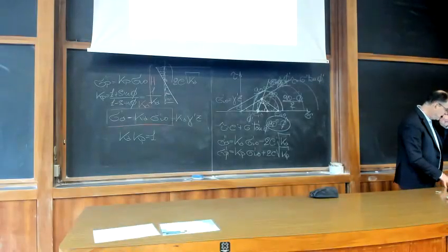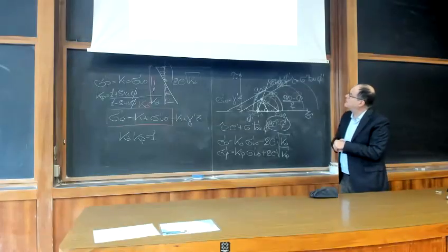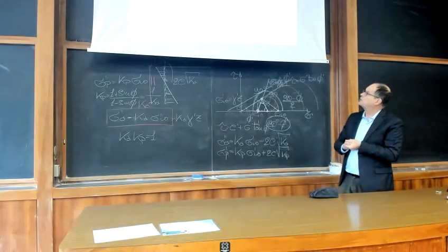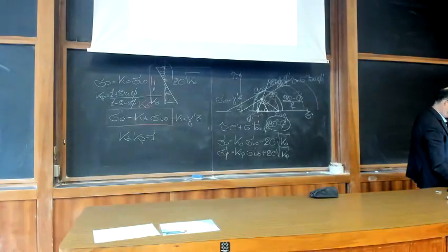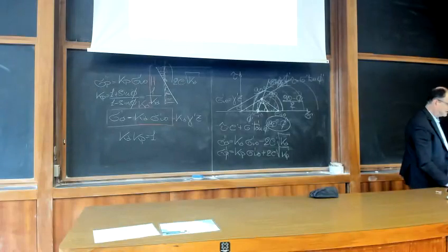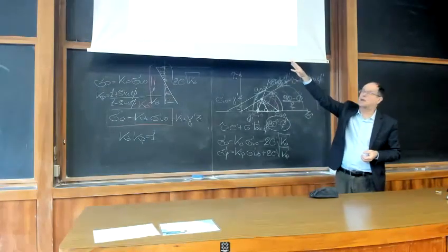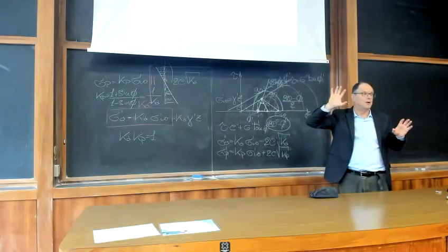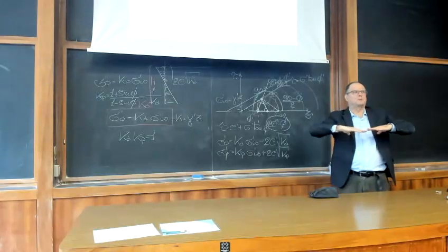Okay? Now, one final point in this slide, which is important to remember, is that the foundation level should be below the depth which is subjected to foreseeable action. But if we go a little bit back to the previous slide, you see we are saying that the depth of your shallow foundation is almost never zero. Your foundation is not bedded on top of the ground.